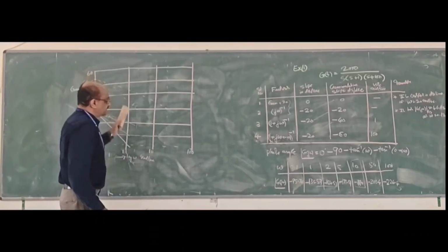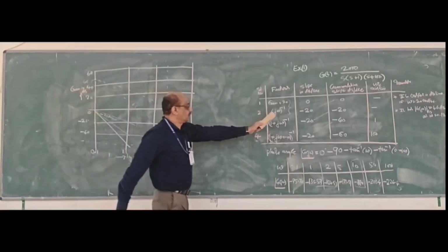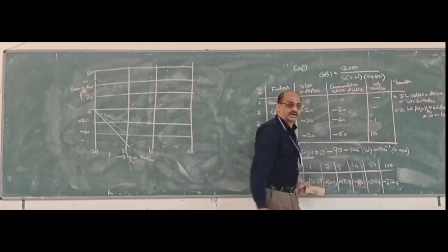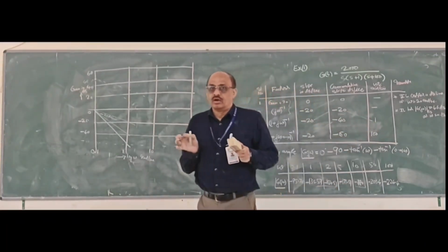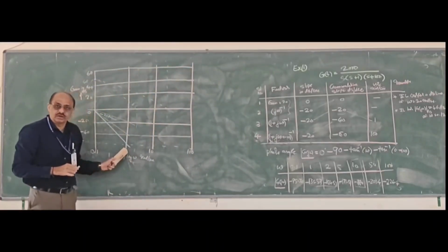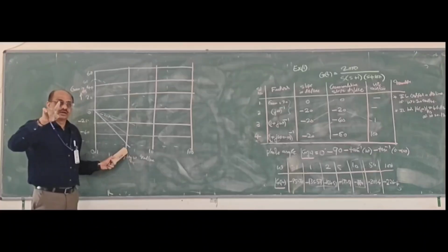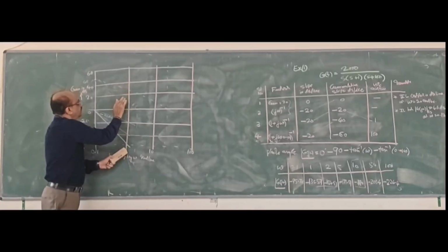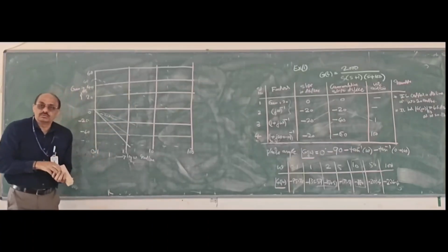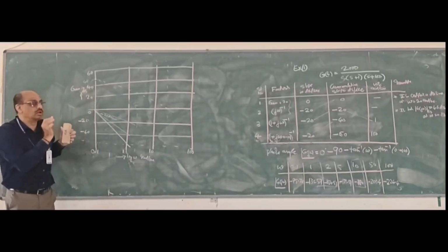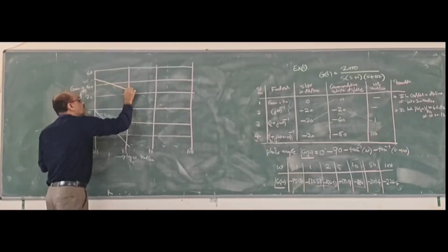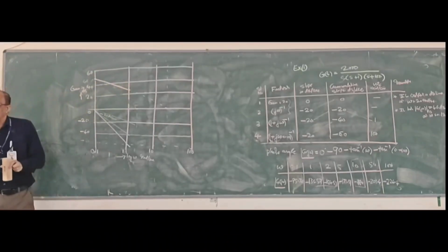Our initial line, which has minus 20 dB per decade according to this, it is telling you that it is minus 20 up to 1 radian per second. Okay, identify the corner frequency. That table is telling you that it is minus 20 till 1. Right? So till 1. So dot that portion from 46 till 1 radian per second.